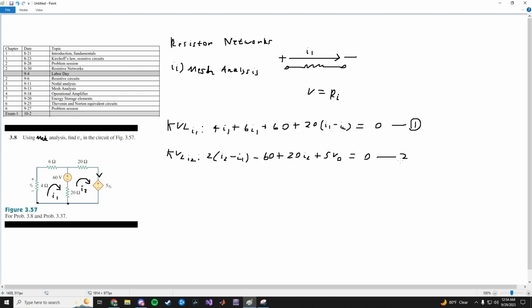That's equation 2. So notice this circuit has a dependent source. So in this algebra problem, well, V0 is this voltage here, which depends on this voltage source. So the first thing you have to do is find V0, which is actually the point of the problem. But you have to use this dependent source because it's 5 times V0 to solve the problem. So 2 equations, 2 unknowns, and that's how you would do it.